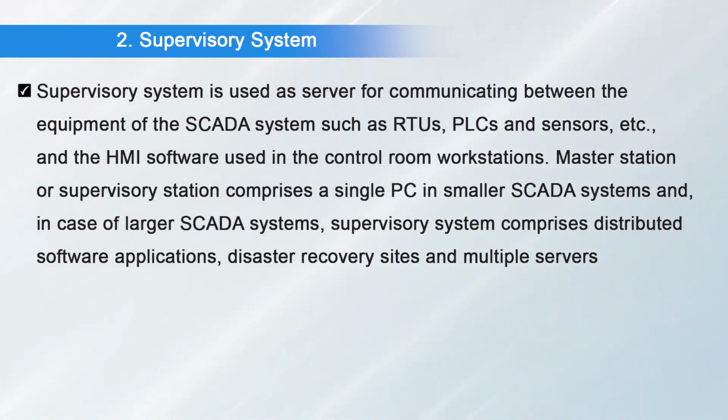Next is the supervisory system. The supervisory system is used as a server for communicating between the equipment of the SCADA system, such as RTUs, PLCs, sensors, actuators, etc., and the HMI software which is used in the control room workstations. The master station or the supervisory station comprises a single personal computer in a smaller SCADA system.